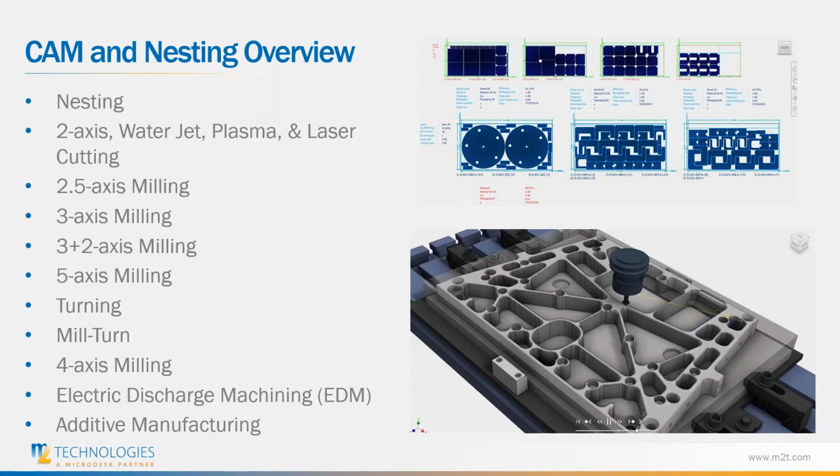Next, we have turning, which typically works on a standard CNC lathe, in which you have a cutting tool, which can move in 2 axes of motion which interacts with a rotating stock in order to create revolved surfaces. Next is mill turning, which allows to have a rotating cutting piece along with the standard turning operations, which is typically used for creating drill holes that align on the outside rather than through the center of the workpiece.